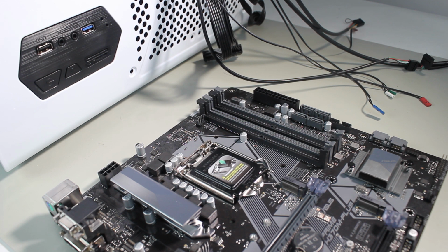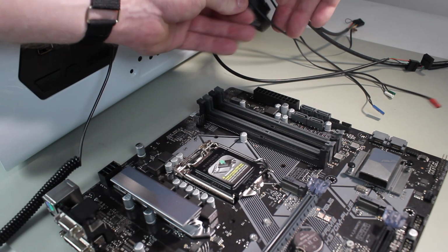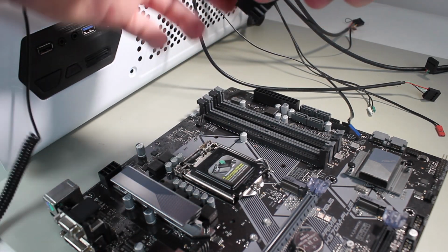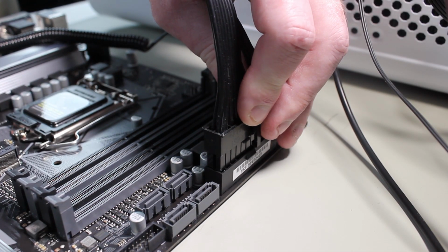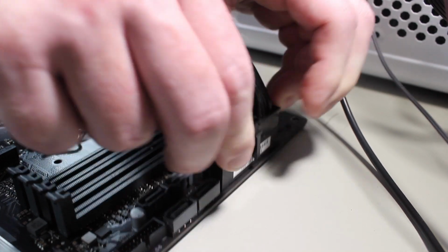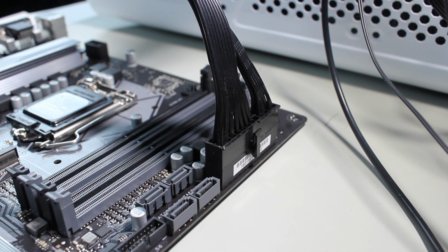To install the P1 connector, it is just a matter of locating the 24 or 20-pin plug on the motherboard. On each motherboard, it will be in a different location, but it should be easy to locate, and most of the time it is near the CPU or memory. Once you find it, it is just a matter of pushing the connector down into the plug. The plug has a latch on it, so when it goes into place, you will hear a click. The connector is keyed so that it will only go in the one way. Pretty much all connectors in the motherboard are keyed nowadays, so don't force a connector into a plug. If you are finding it is not going in, you probably have the connector the wrong way around.